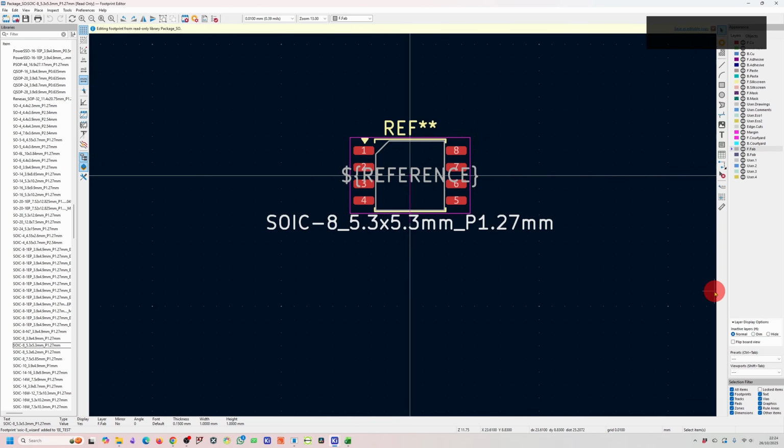So we created a SOIC package using the footprint wizard. You just enter in the number of pins, the pitch, pad shape, dimensions, and KiCAD will generate the footprint automatically. It's parametric, so you can quickly make variations of a similar component without rebuilding them from scratch. I think under the hood, these wizards are written in Python. And if you're a more advanced user, you can script your own to make repetitive work instant, like creating a full range of connectors in one go, if that's your sort of thing.